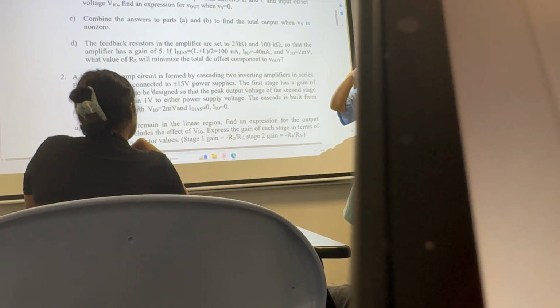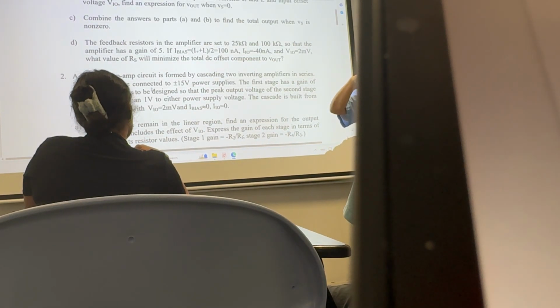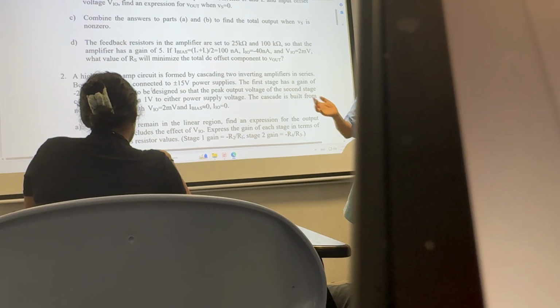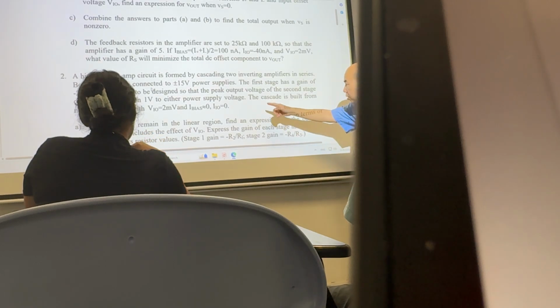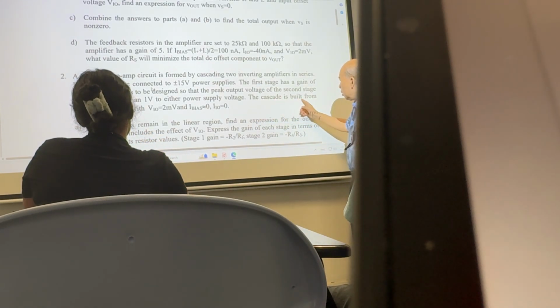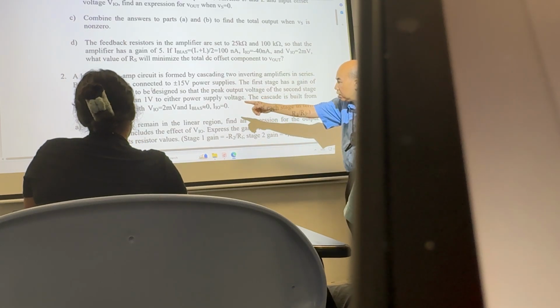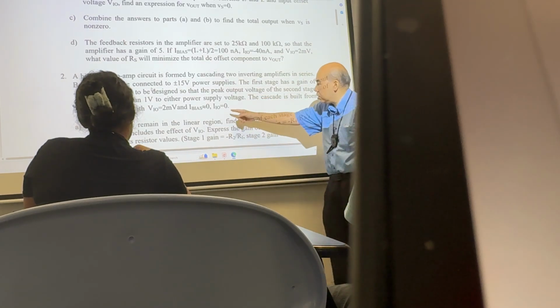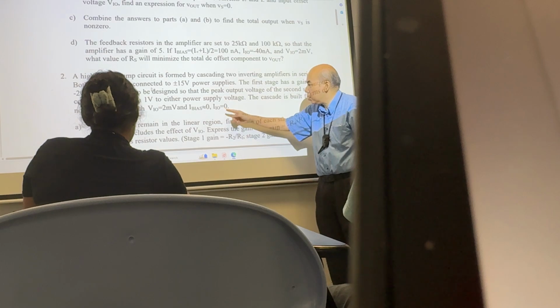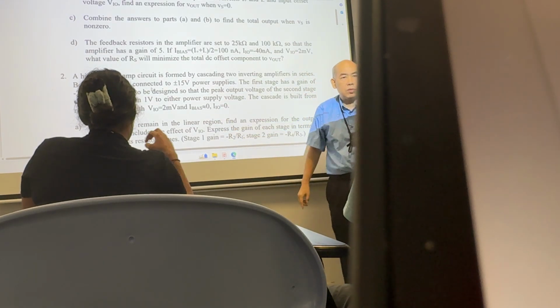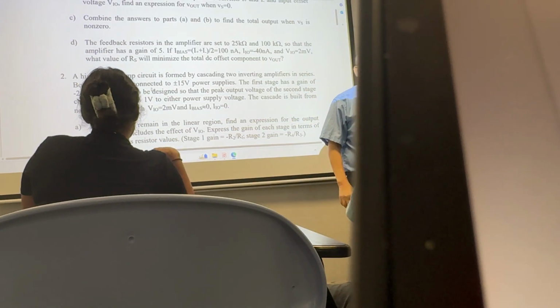But in this case, it is under a saturation constraint, a saturation limit. For a non-ideal op-amp, you can go to a maximum of only 14 volt, and the other is -14 volt. You cannot go more than that. Okay, that is the problem. So this is one. What you have to find, right? You have to see that the offset is given to you. Bias current is 0. IO is 0. What does it mean? If this question gives you that, what is the interpretation?